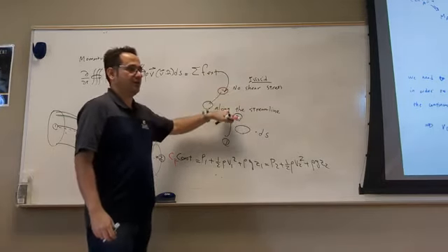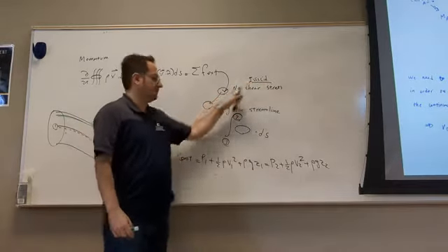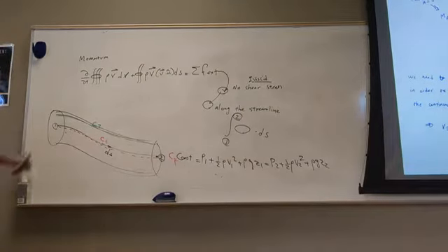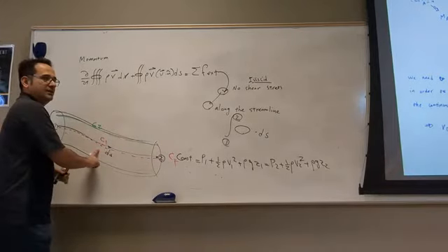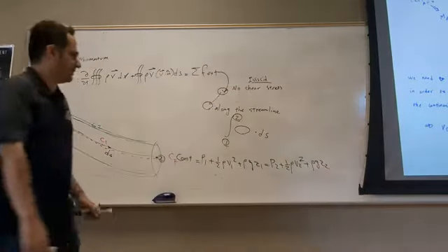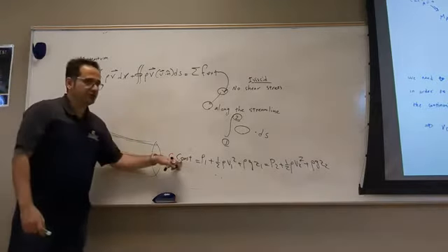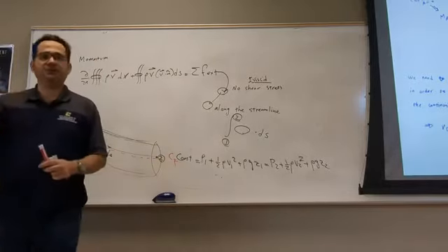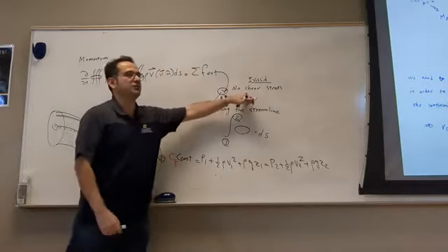So this is a general case. The only assumption in the general case is inviscid. So if you have viscous flow, none of this works. But if you have inviscid flow, you can do this. But C1 and C2 are different. So what does it mean in this problem? Before I go to that application problem, I want to give you one more thing. Later, when we do energy, hopefully next week, we derive this equation using the energy equation, a different approach. This derivation is based on momentum with this assumption, which is only inviscid.